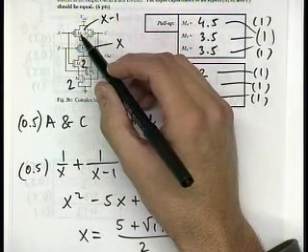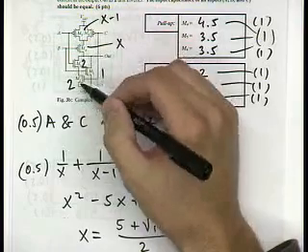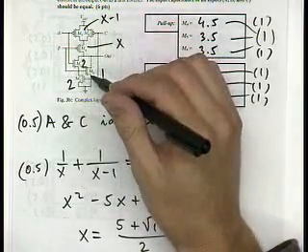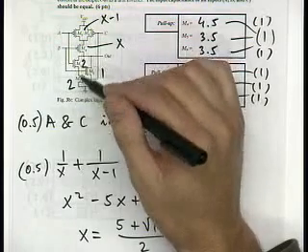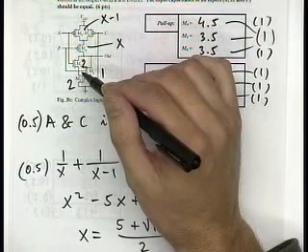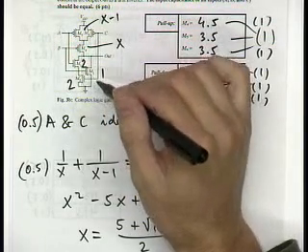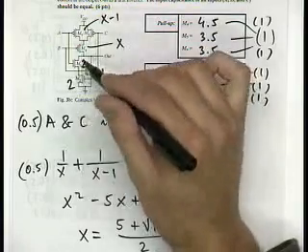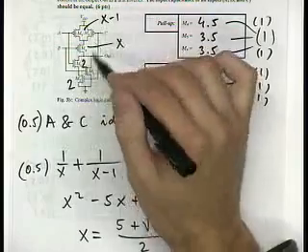That's not good, because it imbalances your input capacitances. And then for the same pull-down resistance, you may end up with sizes of this network such that your pull-up and pull-down are not balanced, because you break this symmetry. It's easier to figure out the pull-down because that's straightforward, a highly deterministic answer. Based on that, you figure out the pull-up.